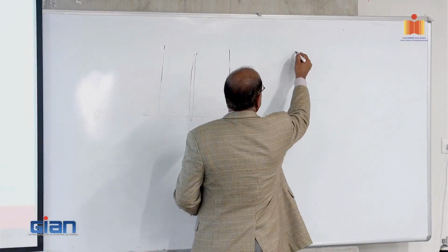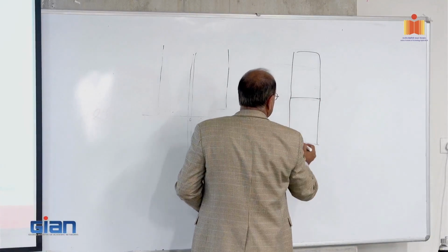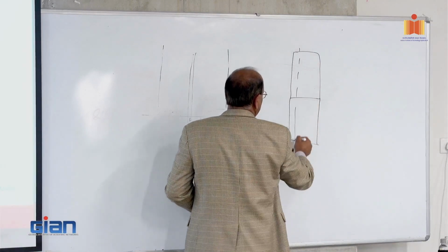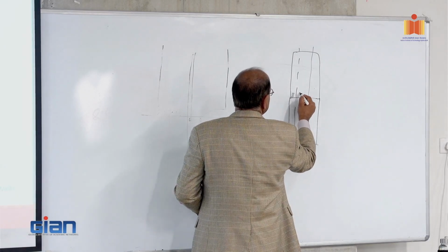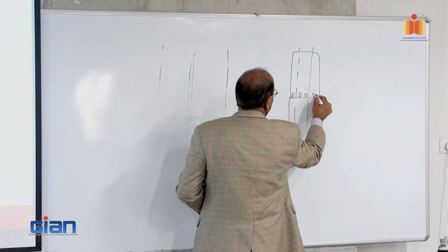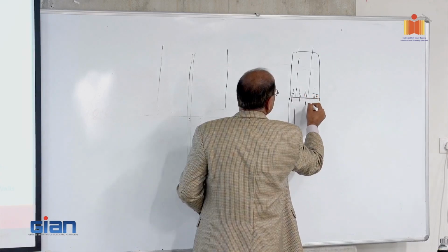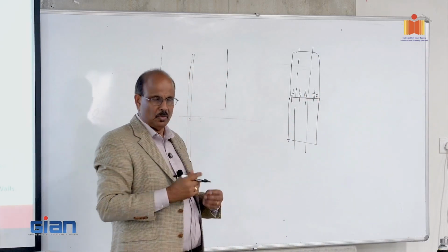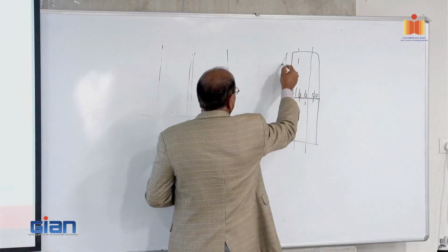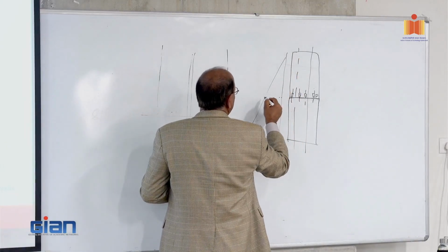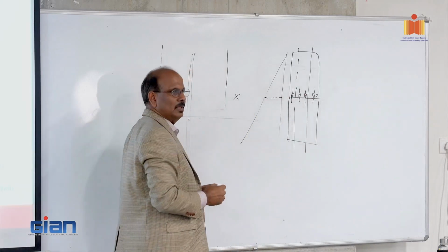So let's say this is one panel, to make it simple. We have a second panel here. So the tendon will be run from top to bottom. Here they will typically use a sleeve connection. That's very common. They will put a grout pad and establish the connection. So these are all connected together. They're not prevented from opening, so it will be designed to be stronger. If you say, for simplicity, this is your bending moment, they will make sure that the capacity here is out here somewhere. It won't open up.